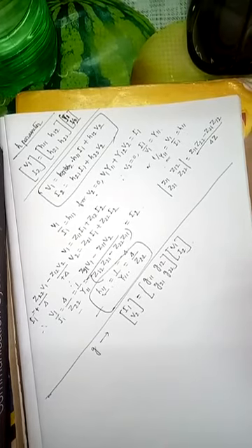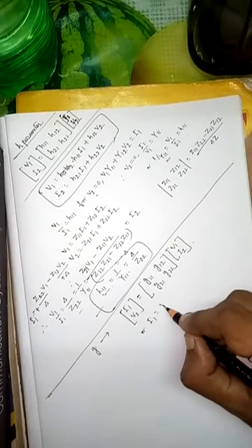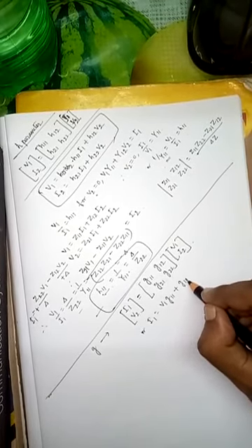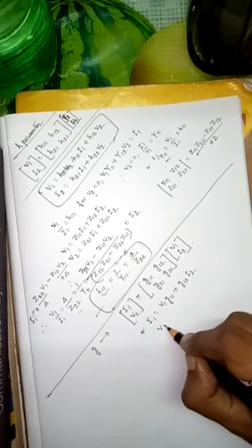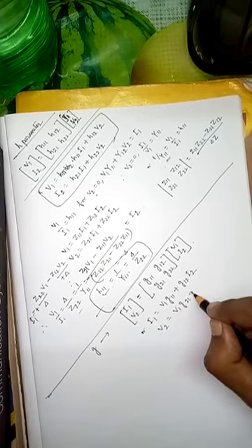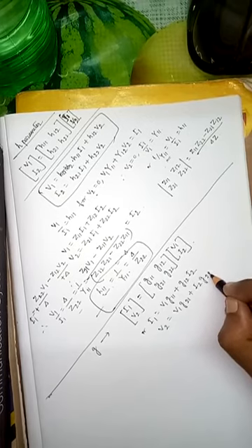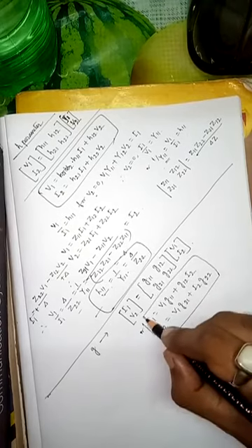Okay, so what is the equation then? I1 equals V1 G11 plus G12 I2, and V2 equals V1 G21 plus I2 G22. That is the characteristic equation of the G parameter.